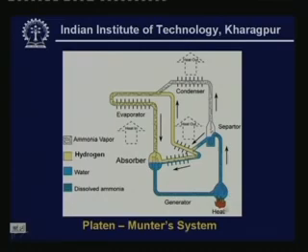Here you can see that the major input is in the form of heat only, and here we use a component called a bubble pump for pumping the solution from a low level to a high level. These systems have many advantages. For example, since you don't have any mechanical component here, they are extremely reliable, and they are also silent in operation. That is the reason why these systems are typically used in small domestic refrigerators, in hotel rooms, etc., where you need silent operation. So the use of these systems is mainly confined to these kinds of applications. However, they are not used in large systems because their efficiency is typically very low.